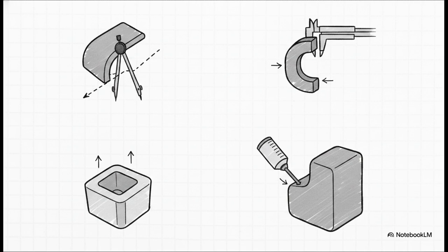First, use a minimum radii of 0.5 times the wall thickness at your transitions to avoid stress concentrations. Keep a nice uniform nominal wall between 2 and 3 millimeters, and make sure to apply 1 to 2 degrees of draft per side for a clean ejection. Finally, always position your gate at the thickest section of the part so the molten plastic can properly pack and flow outward. Okay, let's see how ABS actually stacks up against the competition.